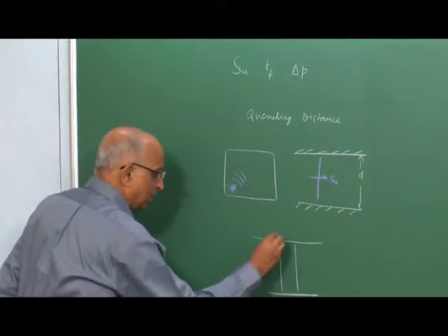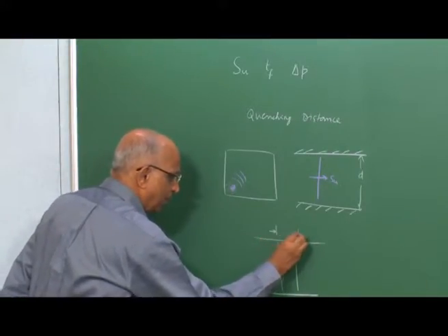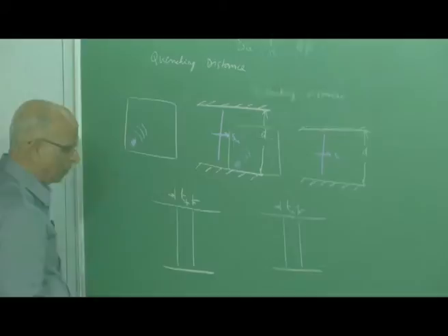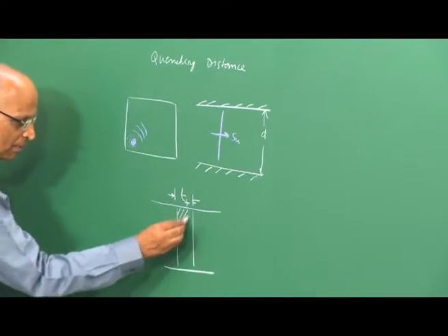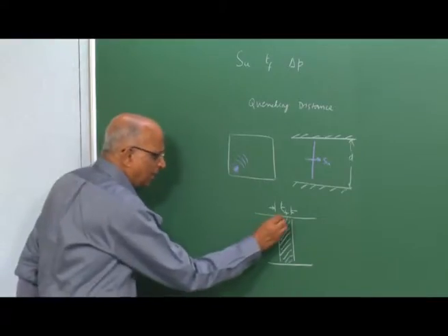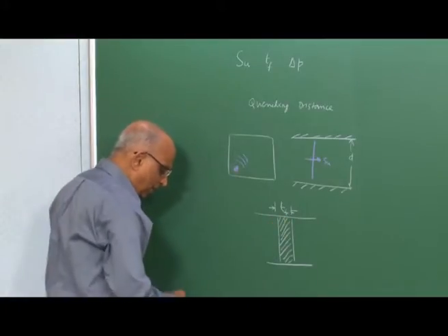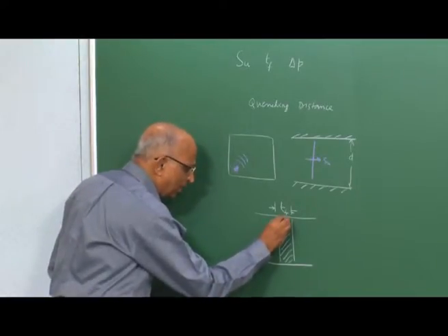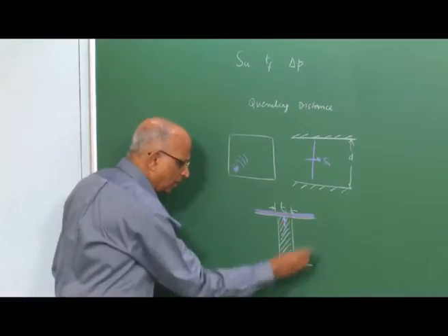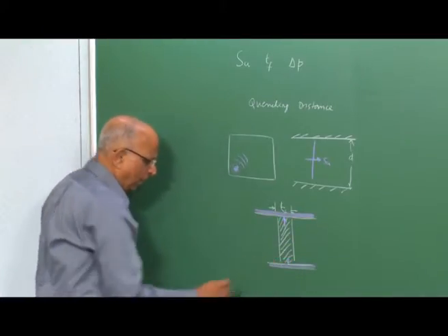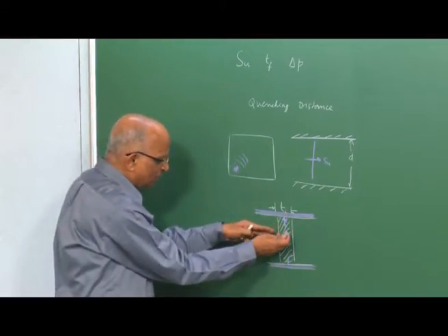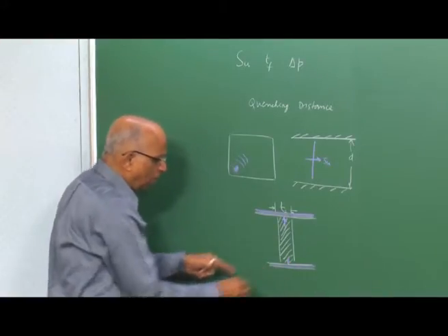Now, I put a particular thickness of the flame which we calculated in the last class as TF, so much millimeter. We found it is quite thin, of the order of a millimeter. Well, this is the flame as it were, and what does the flame do? It allows some heat to get conducted to the wall. In other words, some heat gets lost from the flame to the wall, because the wall is somewhat at a low temperature, maybe of the order of the initial temperature itself, and from this region of hot gases, which is the flame, some heat gets lost to the wall.